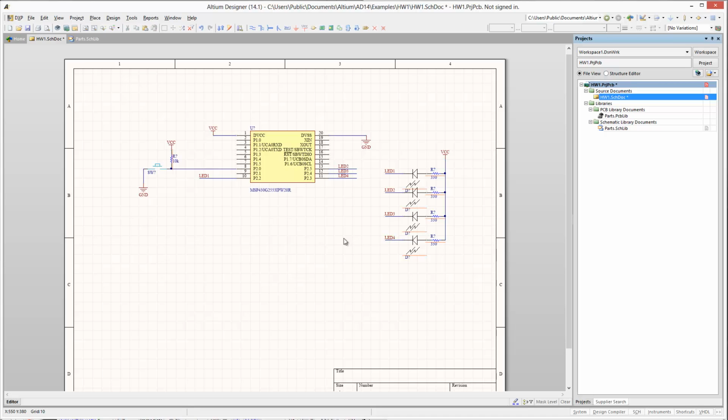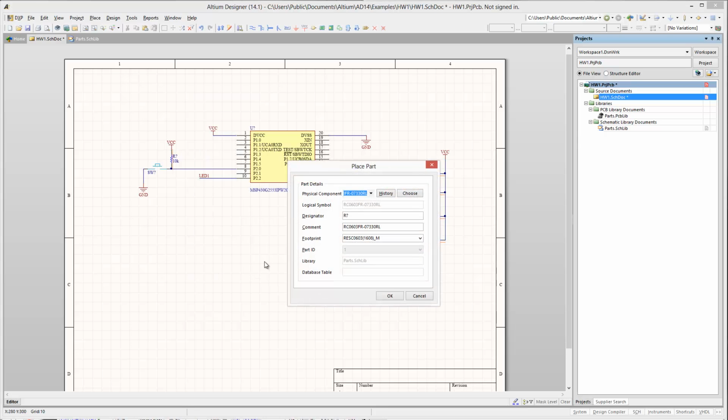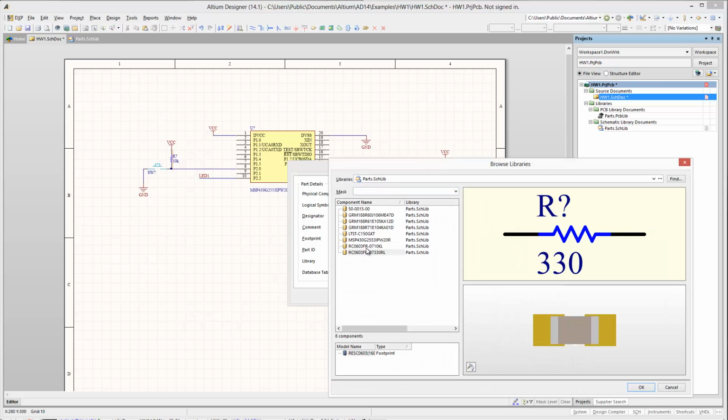And what this makes is that connection, the network is from LED4 to LED4, so these two lines are actually connected in the logic behind the whole device. So there are a few more lines and things that we need to add to this device, and we want a bypass capacitor on the power line. So let's add some of these capacitors that we created.